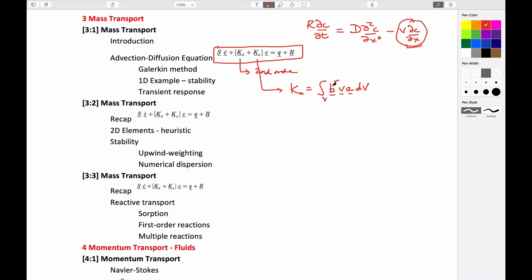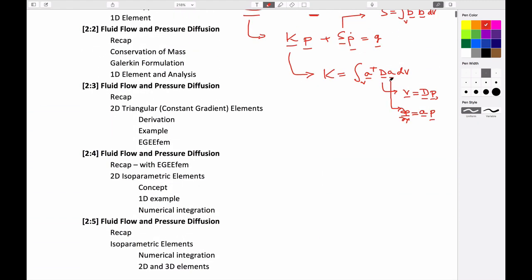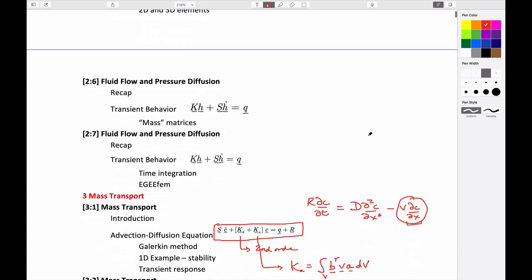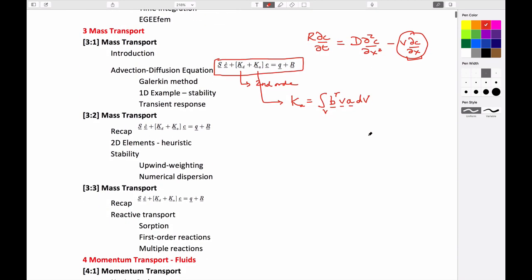And this would be the same as the shape function terms here, which I guess we didn't define, but it might be worthwhile defining. We know that the shape function terms just map, for instance, pressure at the nodes multiplied by the shape functions gives us the pressure at a particular point in the element, any point in the element. And so this would be the part that goes in here. So shape functions, the derivatives of the shape functions, and some constitutive matrix. And so we don't need anything more than that to be able to define these. Here, these are the derivatives of the shape functions, and these are the shape functions themselves. And this is just the magnitudes of the velocities in the element.